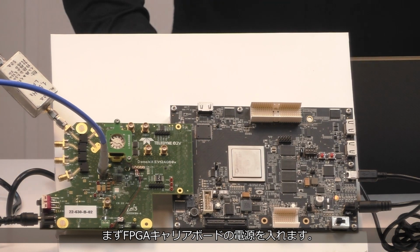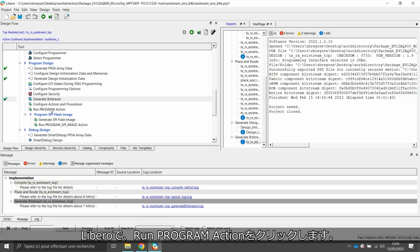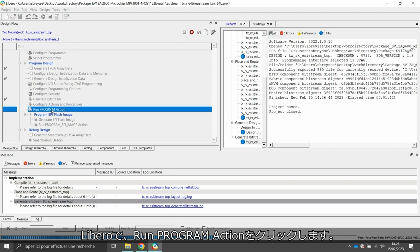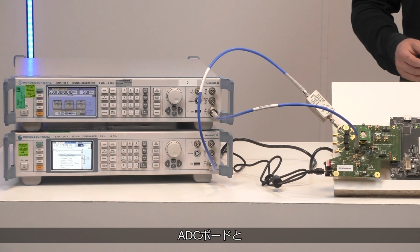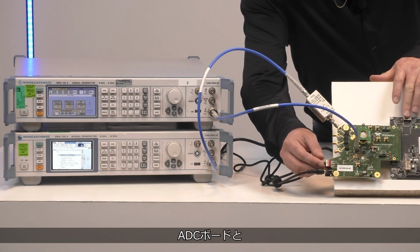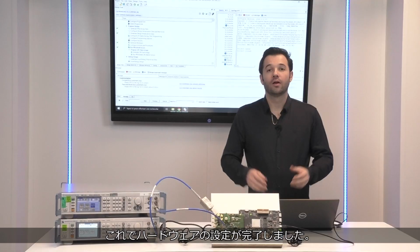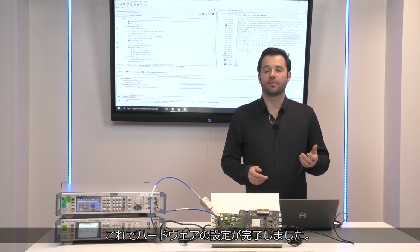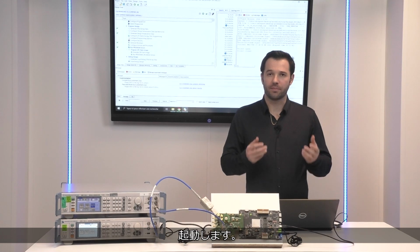First, power on the FPGA carrier board. And in Libero, click on Run Program Action. Now we have programmed the FPGA, we can power on the ADC board and the ADC clock. The hardware setup is now complete. We can launch the graphical user interface using a Python script.